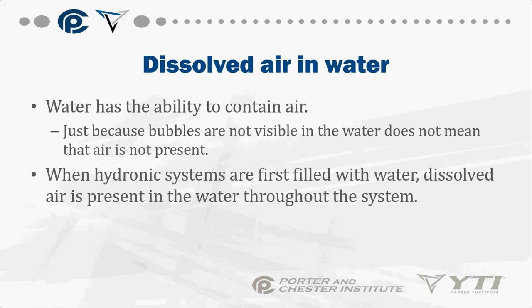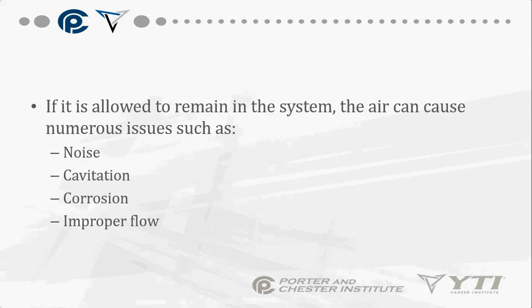When hydronics are first filled with water, dissolved air is present in the water throughout the system. We have to get the air out. Otherwise, you are going to have noise. You're going to have cavitation. You're going to have corrosion. You're going to have improper water flow, and it just makes for a bad day.